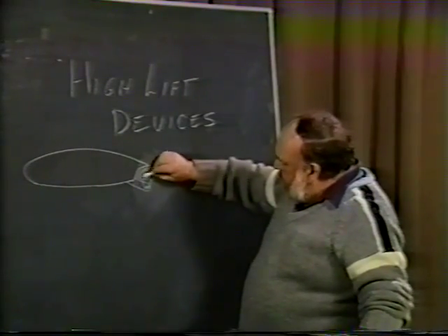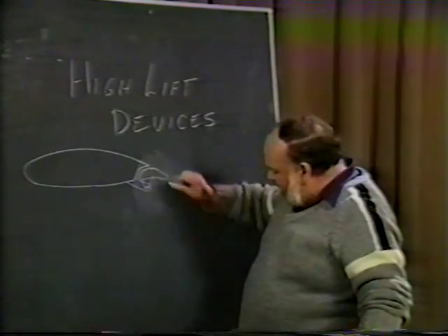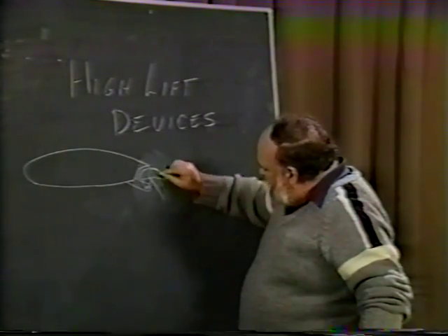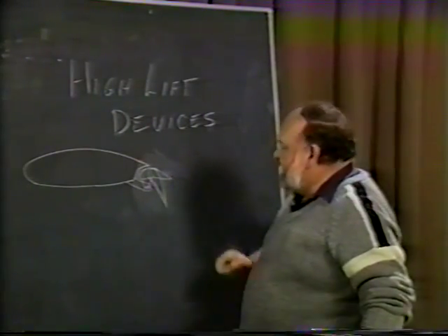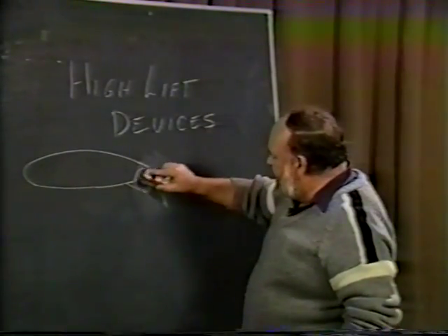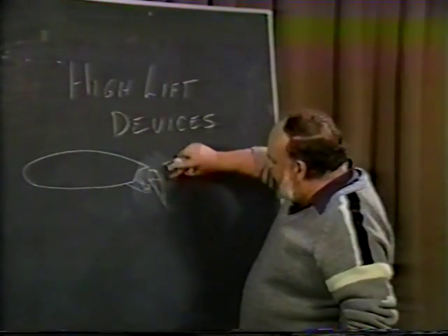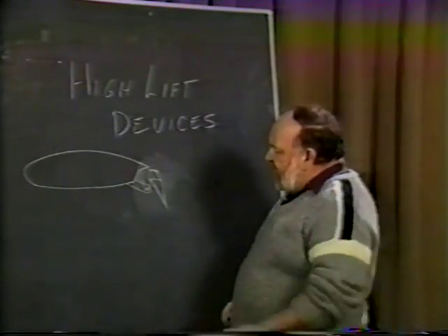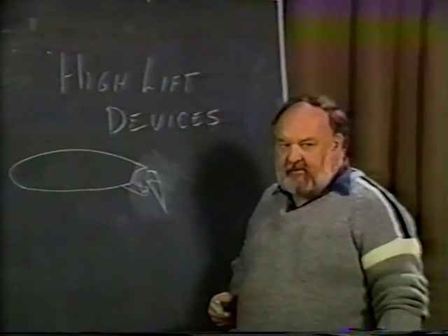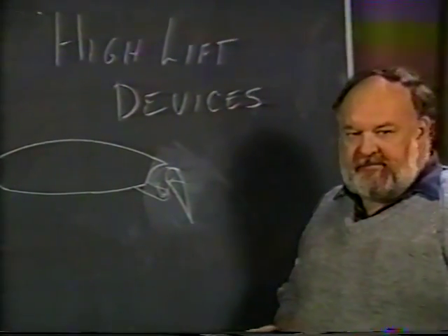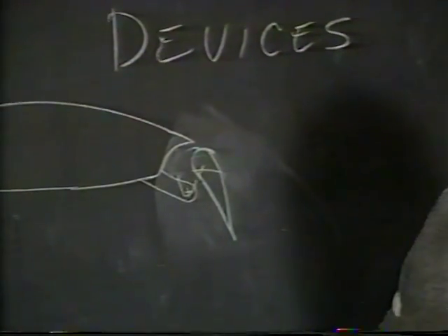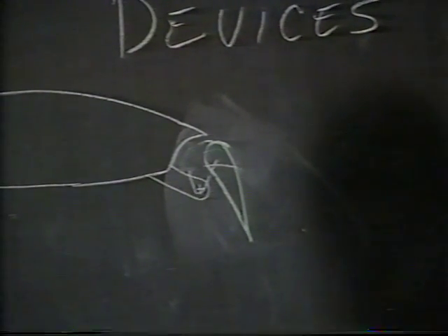And then this flap pivots back, and in the deflected mode, will look like this. Now what happens here, when the flap is down, and let me take care of the one that's up in there so we get a little better look at this thing. What happens here is this slot, and it has to be very, very carefully built and laid out. When you check on the data and look up flap designs and characteristics, you have to follow the coordinates of this slot arrangement rather closely because it's critical.